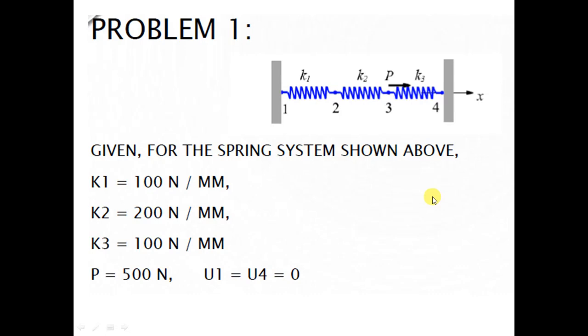So let's start by taking a simple spring problem. The difference between the spring and the stepped bar or truss problem is that in the spring problem, K is directly given. K is nothing but the stiffness of the spring, but in a stepped bar or other problem, we have to calculate K first and then write it. So this is the problem.